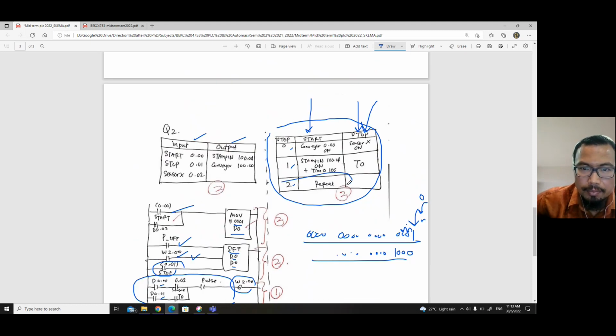This is already a repeat, so you use D0.00, D0.01, and here to repeat is D0.02. That's why you must have D0.02, because repeat is the same as pressing the start button again. You push the value 0001 into D0 again, but here without using the start button.